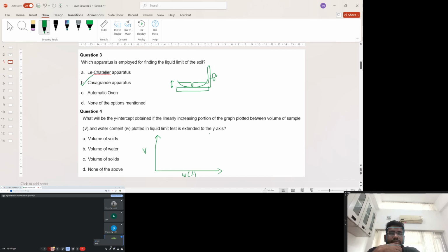Once the water content starts decreasing, the total volume starts to decrease. That continues up to a certain point, which we term the shrinkage limit, and in between we have the plastic limit, and at any point we have the liquid limit, and further it is a slurry.